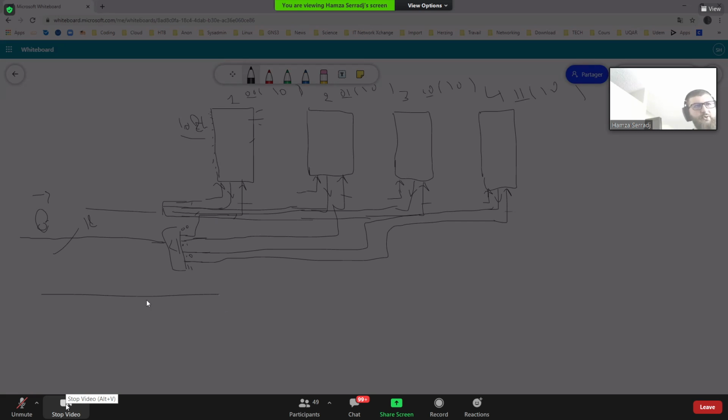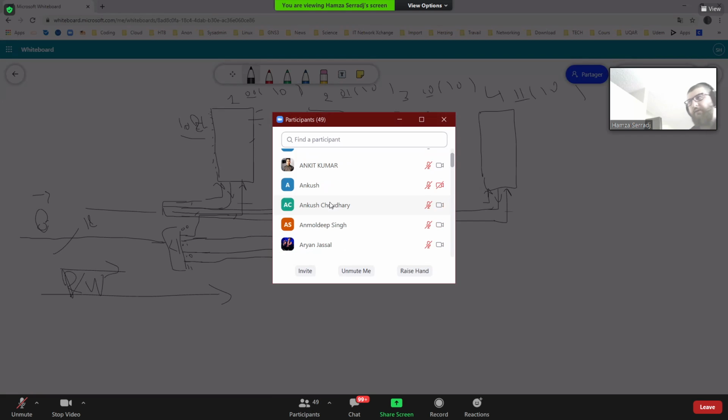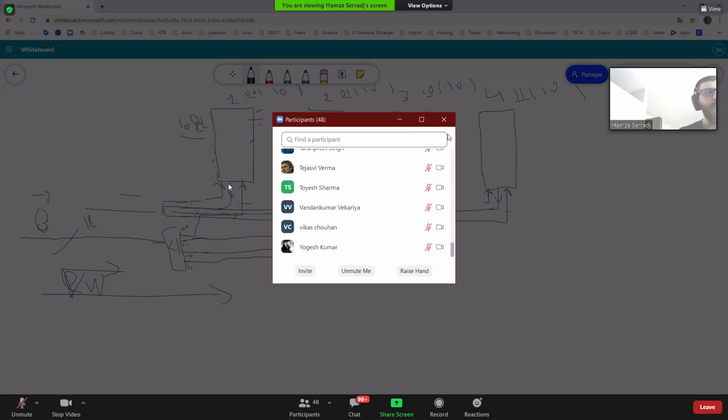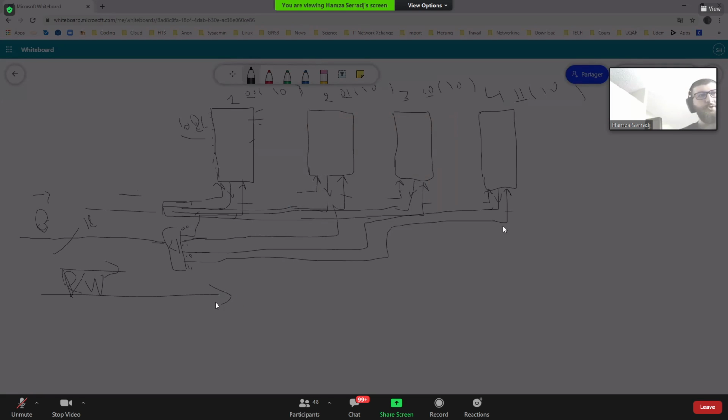And of course, at the end we're also going to have some instruction, right? Read or write, that final line on those chips that says we're going to enable the input bus or the output bus. So if this one is 0, the input will be enabled. If this one is 1, the output is enabled, and so on. That's it, right? And this one will go everywhere too, but the width is just 1 bit here. It's not several bits anymore. It's just 1.